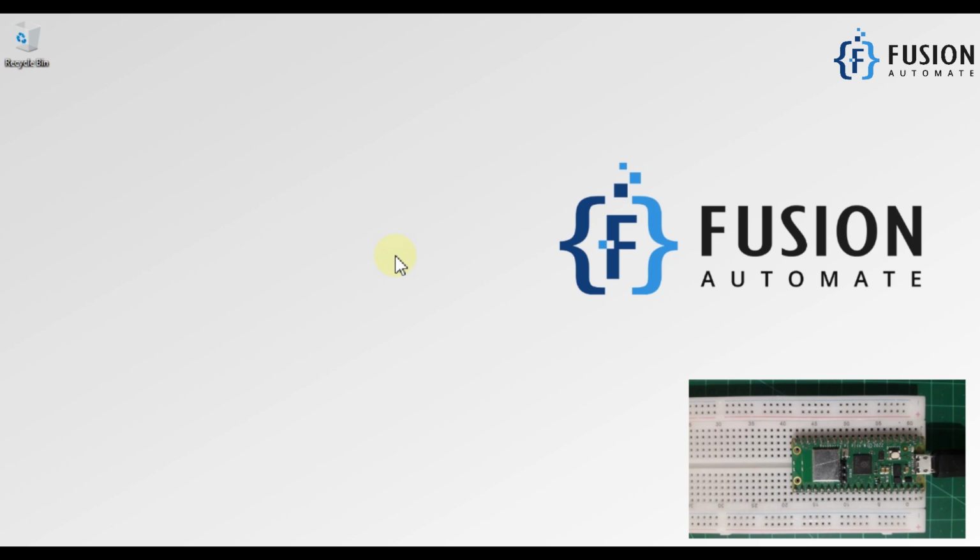You can see here I have connected my Raspberry Pi Pico W to my system, to give power to it and to program it with the help of Thonny MicroPython IDE. So the main target of this video is to make our Raspberry Pi Pico W a Modbus TCP client to read holding register values from our remote Modbus TCP server. So first let me set up our remote Modbus TCP server.